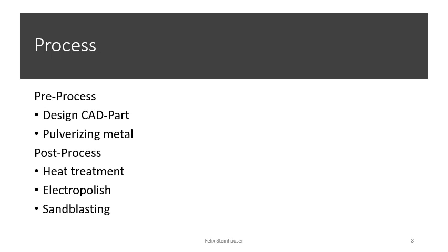Then you have to pulverize your metal. Mostly you buy it from the supplier who also designed the machine. Then you can print very quickly. You take the design part, put it in the software that works with your machine, and this automatically slices it. That means it cuts your design part up into thin layers, which are later used to build up the part on the 3D printing machine.